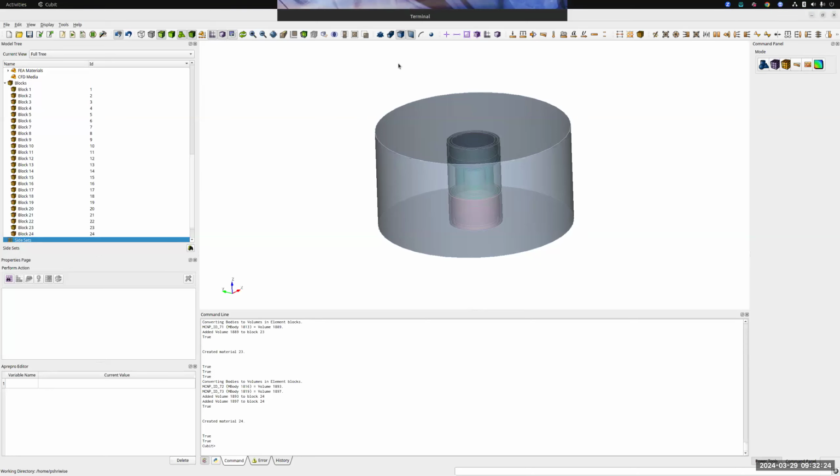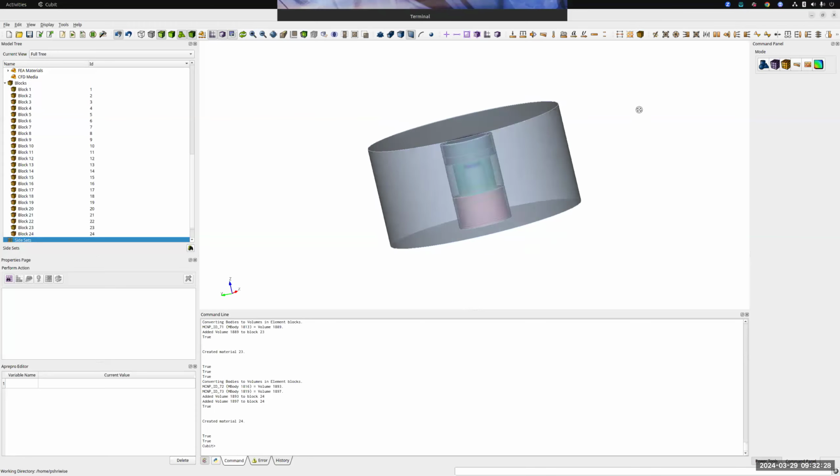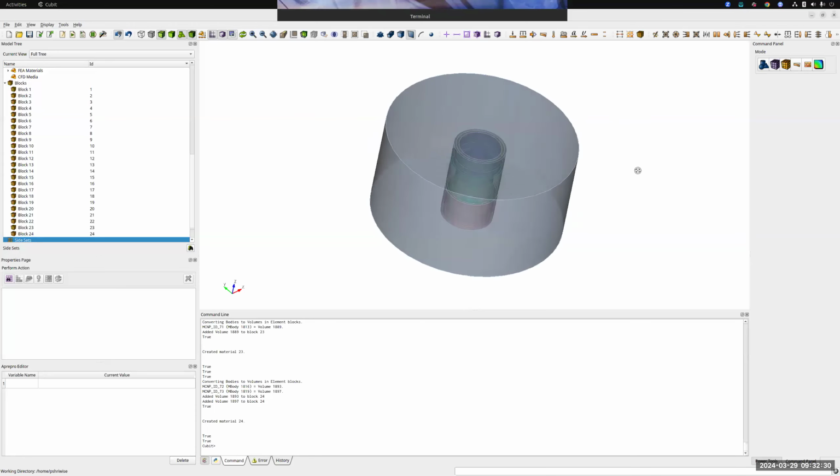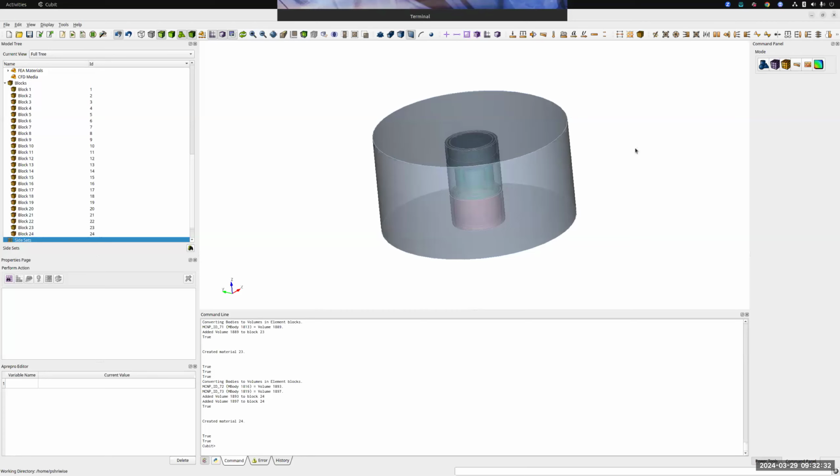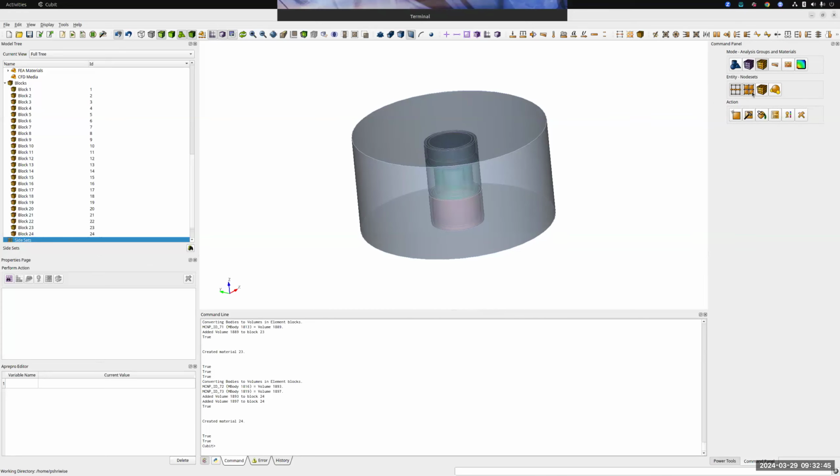Okay. So I will switch to selecting some surfaces, and really here, this boundary of the large cylinder surrounding our core is meant to represent the exterior of the reactor room or experimental space. And so what we can do here is create a new side set. I'll do this all through the command panel. So I want to create a side set. The ID is not particularly relevant here.